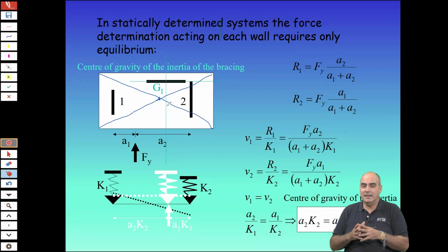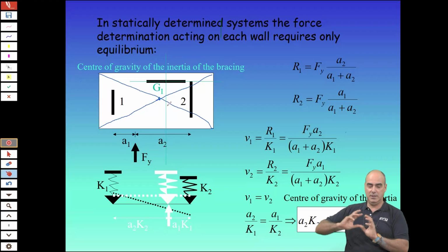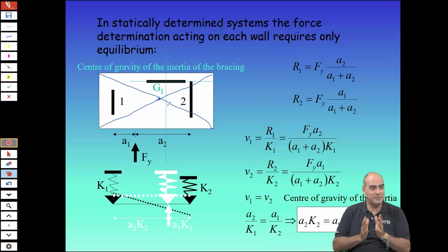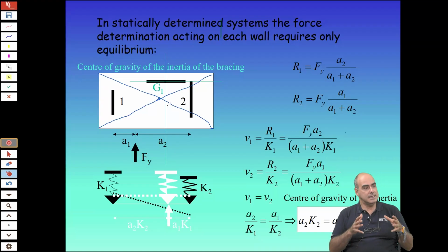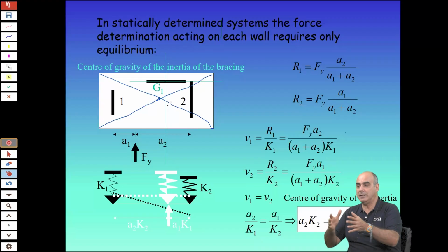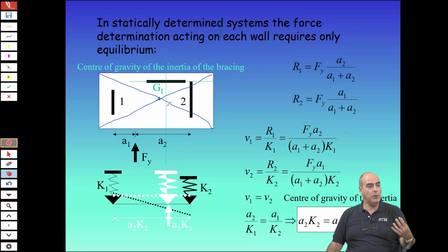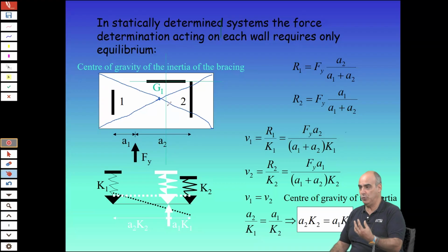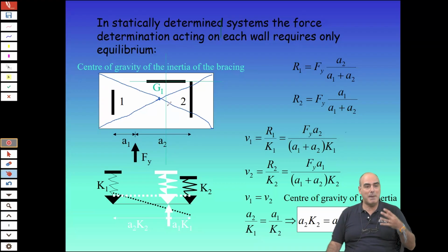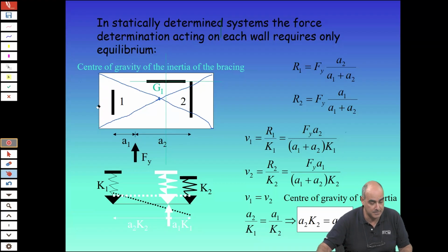So an architect comes and he says, no, because I want something strange, then the fighting starts. But it's okay. This is the first way to guarantee a good behavior under earthquake. Then the rest is a matter of analysis, a matter of detailing and so on. But this is something which comes beforehand. It's part of the conceptual design. So the building must be, as much as possible, regular, because this governs a very good response under earthquake, but most of all, reduces the torsional effects.